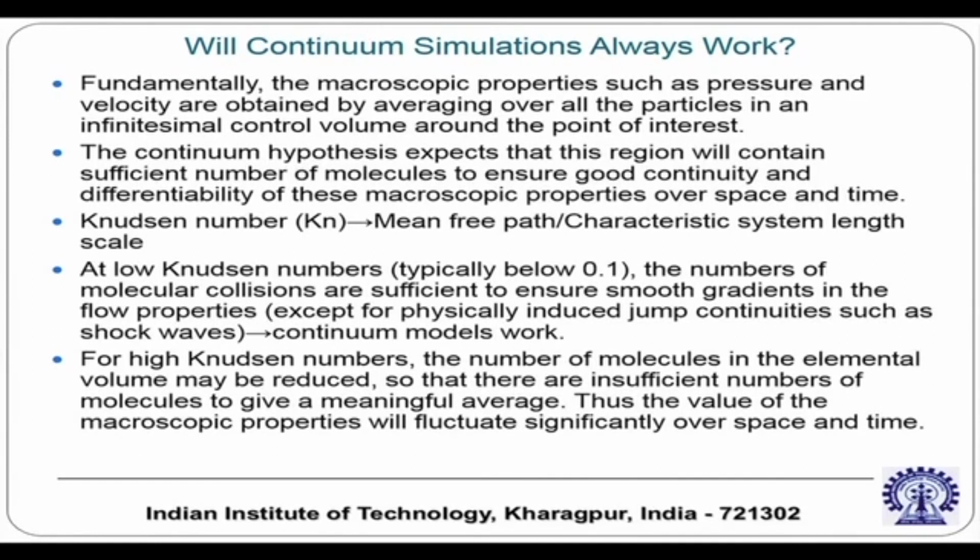However, if you go for higher values of Knudsen number, then the continuum nature of the flow is destroyed and the discreteness of the molecular entities becomes important. When this discreteness becomes important, then you have to use typically either molecular dynamics or a Monte Carlo based simulation, which is known as direct simulation Monte Carlo or DSMC.